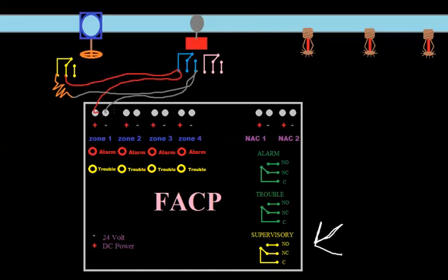We're going to go through. We're going negative to the flow and back out, right? It's not going through those contacts. It's going back out. We're going through our resistor, through the relay on the tamper, and then back to the panel. So there is current flowing. We have a complete circuit there. And I know this is kind of sloppy, but it makes sense. If one of these sprinkler heads bursts and water starts shooting out of here, this flow is going to activate, which will short.